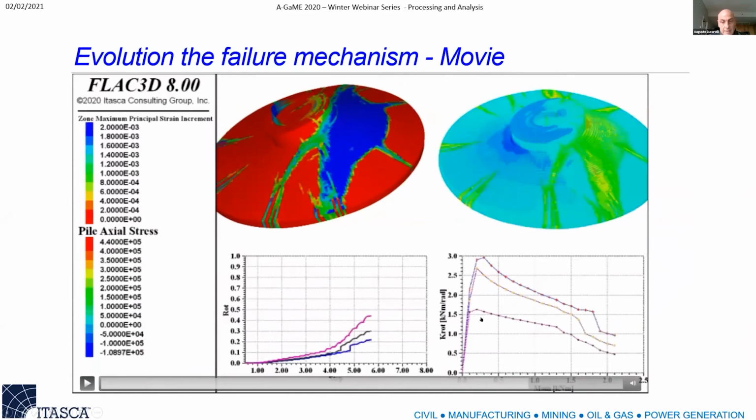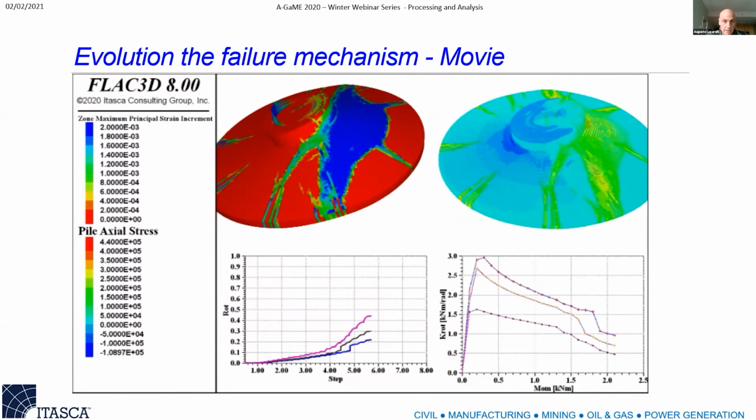And to show what's happening in progress, you see the progression of the failure on the concrete side. So this is something that is interesting also for the numerical side, that is not only related to the geotechnical aspect, but sometimes is the combination of structural and geotechnical that needs to go together to try to understand better and optimize where the resources should go. Is it better to invest in a stronger concrete or to try to do ground improvement? It wouldn't make any difference here to ground improve other than improving maybe some concrete detail.